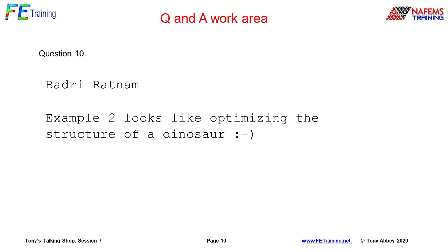For example, a lot of very successful shape optimization is done just to improve stress concentrations locally around features to improve fatigue life. So we're not coming up with any kind of radical solutions, we're just perturbing things a little bit. And again, it's very difficult to figure out how to do that kind of thing intuitively. So let the shape optimizer in that particular case move that surface around until we've got a much better fatigue life.